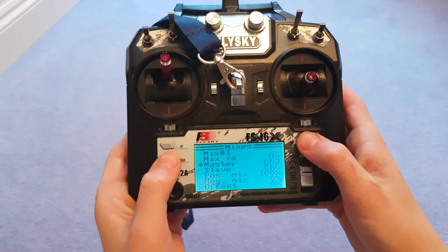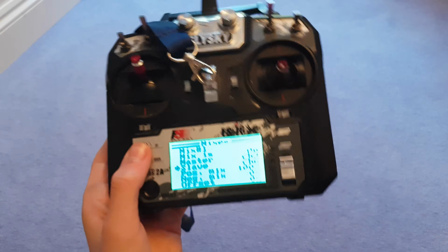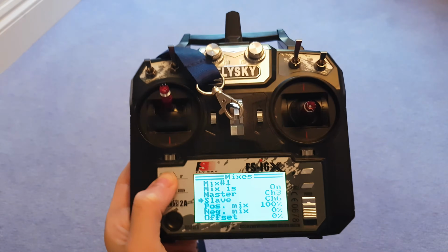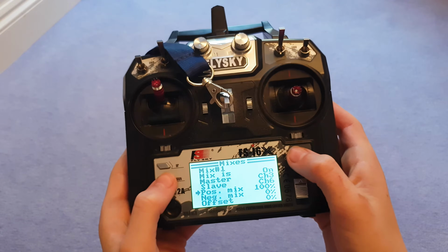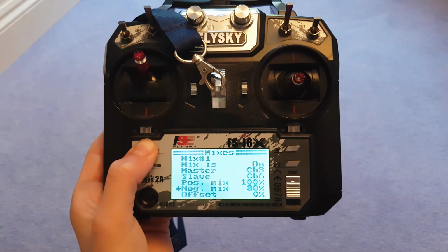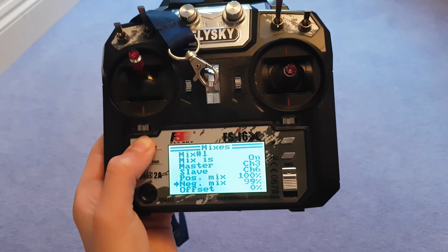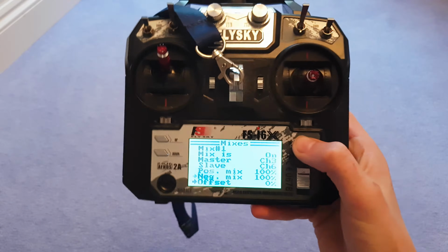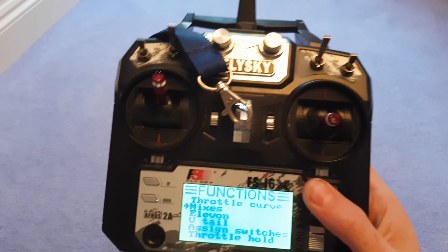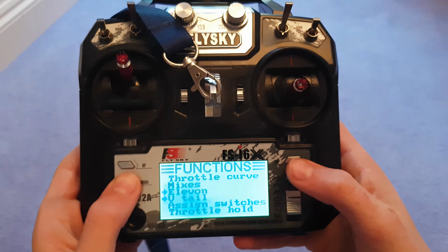Right, so the slave is going to be the one which actually selects it. So you just press OK, get to slave, and you select that to whatever channel. This one is going to be channel 6. So you want 100% on each of these. I always do 100%. And offset, I always leave that alone. So just click off, and there we go, cancel again. That's pretty much the basics of setting up a mix.